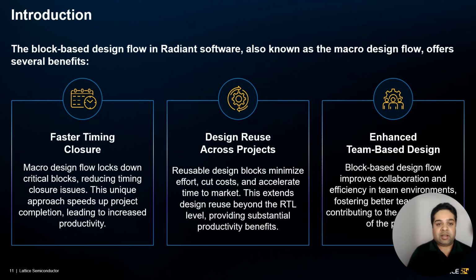Block-based design provides a faster timing closure. This approach helps in locking down critical blocks early in the design process, which reduces timing closure issues. By focusing on the critical blocks, the overall project completion time is sped up, leading to increased productivity.